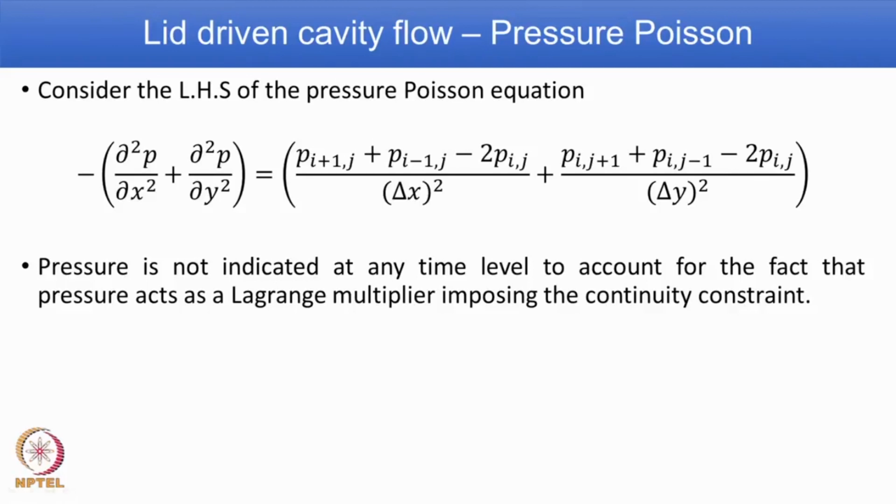Pressure is not indicated at any time level, to account for the fact that pressure acts as a Lagrange multiplier imposing the continuity constraint. That means, the pressure is only local at that particular time.